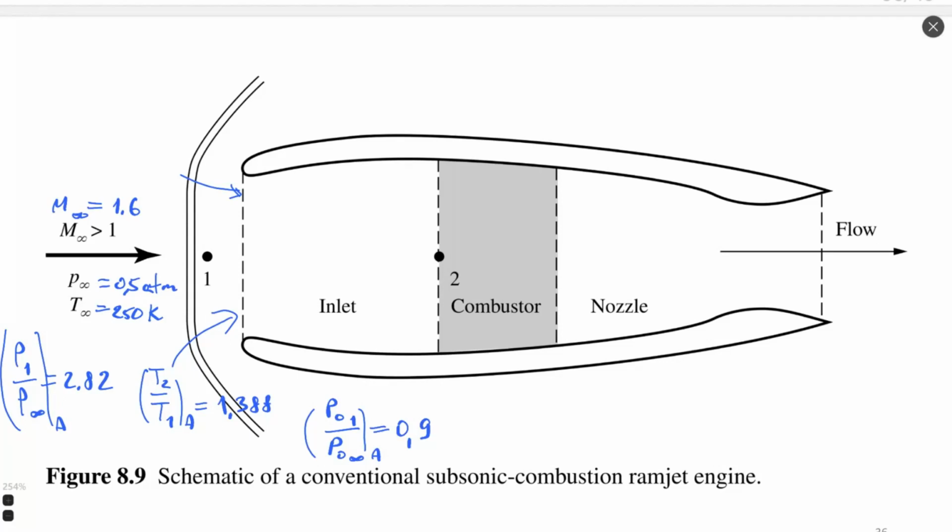So we lose 10% on this transition. I think it is reasonable to have thrust and to fly with this loss. Already on the limit, because losses of 10% are quite significant. They are quite big, in my opinion, but still possible to fly at this velocity. For example, if we lose already 20-25%, it will not be viable at all to create an engine for such conditions.